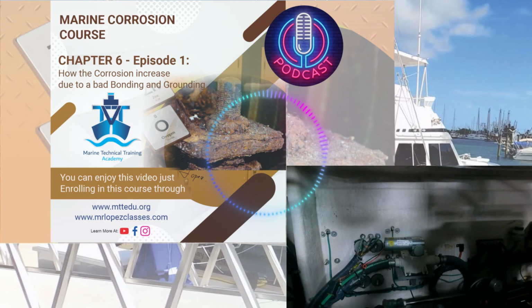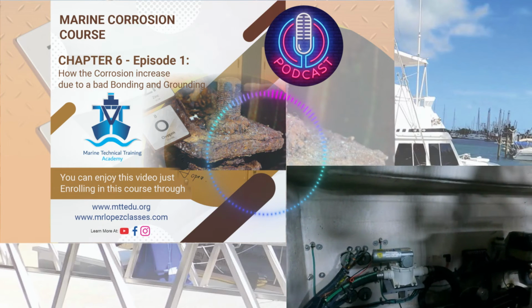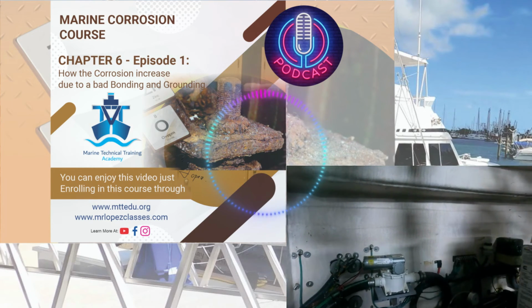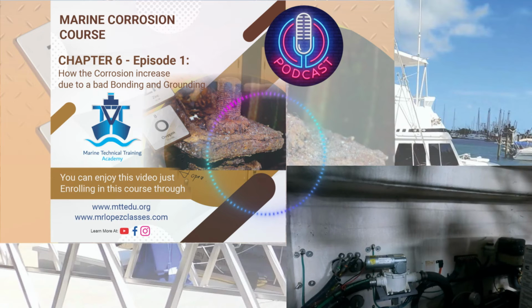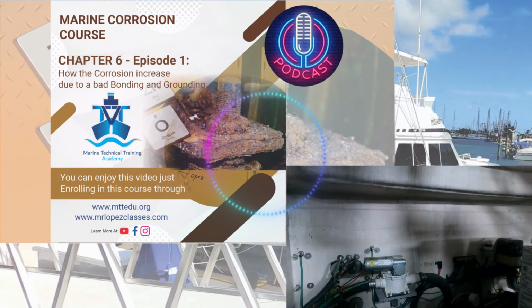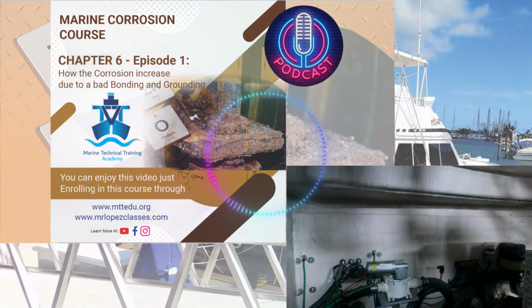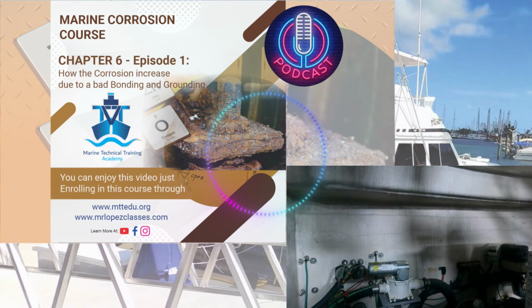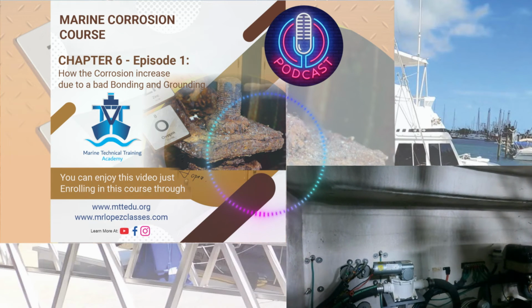Now we are going to check the voltage in this direction. Normally, if the galvanic isolator is in good condition, the voltage rises from 0 volts until 0.9, maximum 1 volt. If the reading is 0 immediately when you connect both terminals, it's because the capacitor internally is defective. If you read 0.9 immediately, it's because one diode is shorted. If you read 0, it's because both diodes are open.